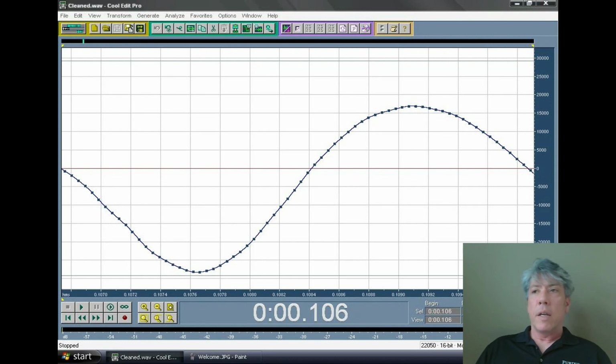Now if you're talking about the distance between the Earth and the Moon discretized into only 65535 different levels, that's going to be a much longer distance per change, or per least significant bit transition. And what that really means is, when you've got a 16-bit number, what happens is the least significant bit is constantly flipping back and forth as the count that string of bits represents increases.